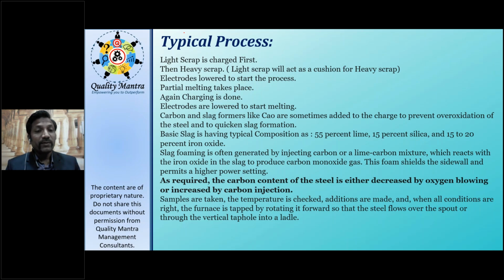because otherwise what will happen, the oxidation will take place of the iron. It is not a sealed one, na? There is oxygen always present on that whatever the earth is there, so oxygen will directly react with the iron to form iron oxide. To avoid that one, we have to form the slag on the top. And second thing is that